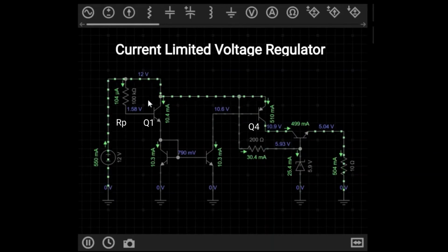There are certainly many ways to implement a current limited supply. This one just shows how a current mirror could be the basis for some of them. For the circuit as shown, the output current limit value for high beta transistors would be approximately the current through this reference resistor multiplied by the beta of this buffer transistor multiplied by the beta of this output transistor here. And that is shown by this formula.